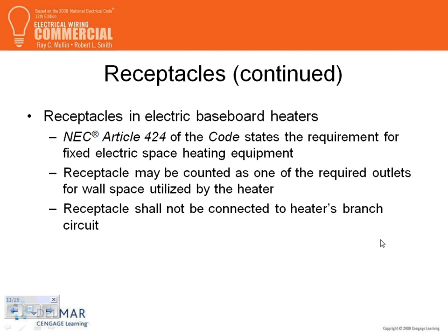Okay, so that's basically what this is. If you use baseboard heaters, you might in a commercial building, guys, because somebody's office is so cold since the mechanical engineer screwed up the heating and cooling system, so they put in a baseboard heater. Normally you don't do that, but you might have a situation where a baseboard heater is your application. You need a receptacle in that location for whatever reason. That receptacle can be part of the structure of the baseboard heater, but you have to feed it from an independent circuit. So that's what this is telling you.